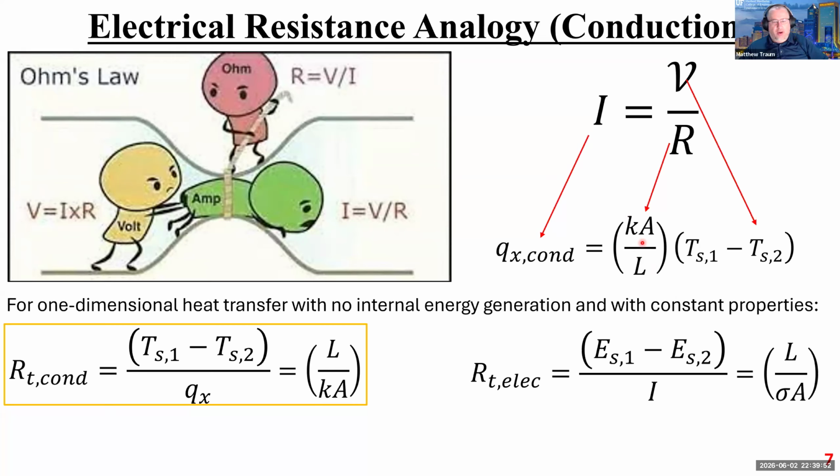Okay, so what I want to do then, because I want to get into that world where I can use everything that I know from electrical engineering to model these one-dimensional heat transfer processes. So I want to write something that looks like a resistance, so I can then use resistances in series, resistances in parallel, all those equations to get my temperatures and my heat fluxes.